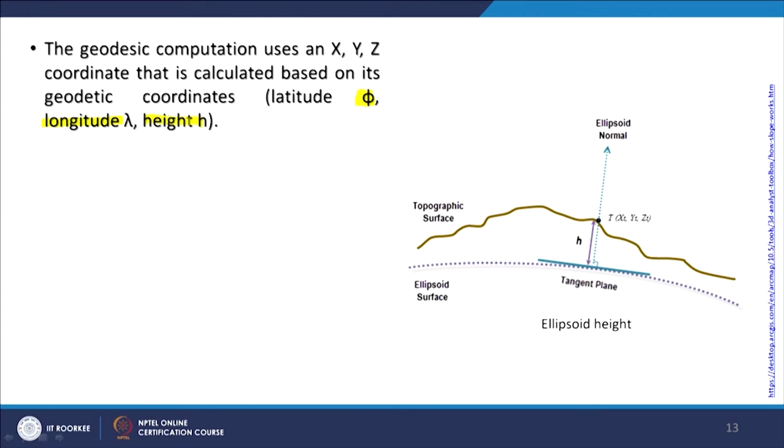As I have mentioned, more complications will come once you go for more accurate estimations of slopes. I am still using the word estimation because, after all, a digital elevation model is a model. It is not a complete true one-to-one scale thing. The real one is on the ground only.